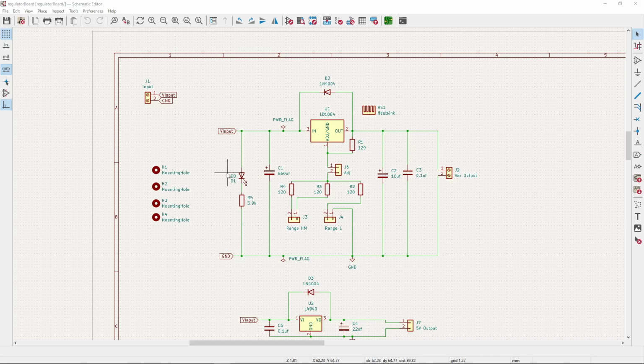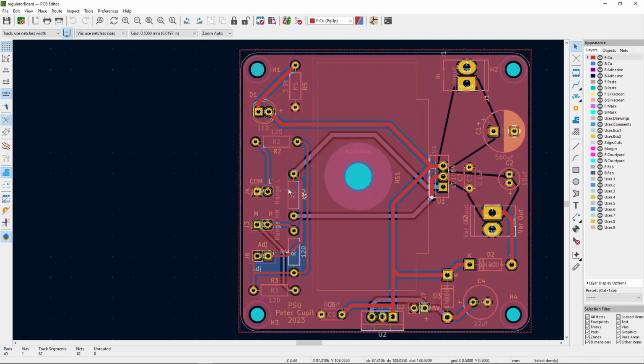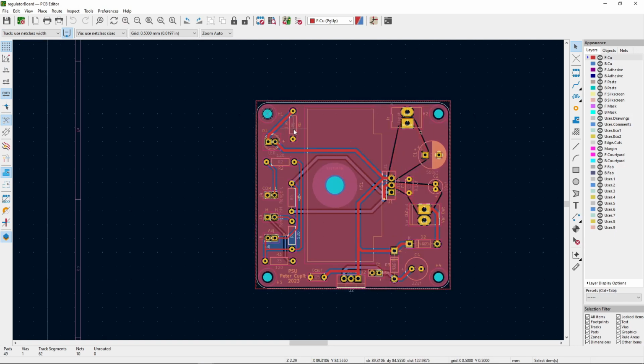I've also added an LED. It'll be a high intensity LED. That's why the resistor is so large. That's a bit of a guesstimate. I calculated it, but I'm not sure which LED I'll use yet, so I don't know. The specs shouldn't be too different. I like using the high intensity ones because they can light up with very small current. So the board's been modified slightly. The LED and its dropping resistor is here, and those two diodes are here. I've also rounded the corners.